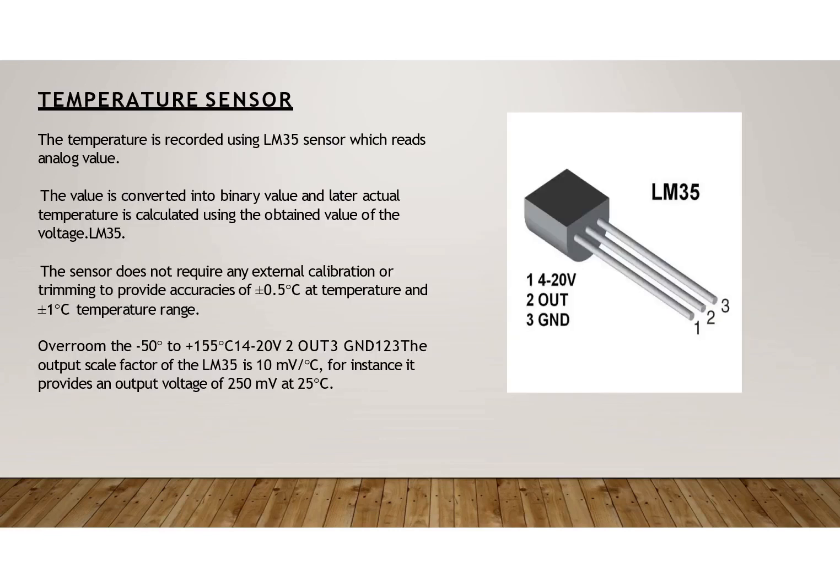Temperature sensor. The temperature is recorded using the LM35 sensor, which reads an analog value. The value is converted into a binary value and later the actual temperature is calculated using the output voltage of the LM35.